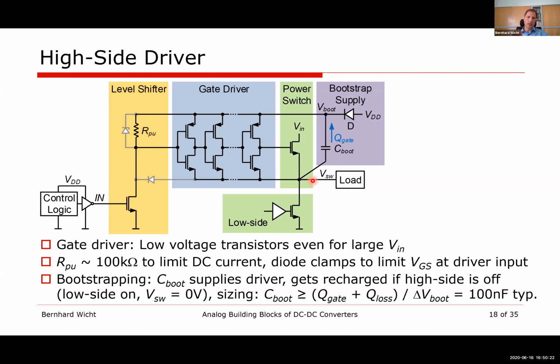So, if we have an external power stage, this really matters. We get some local LC tanks which are parasitic and which cause some ringing, and that's what you're mentioning. If we implement the power stage on chip, it's a little bit easier. That's something I feel we spend a lot of effort on.